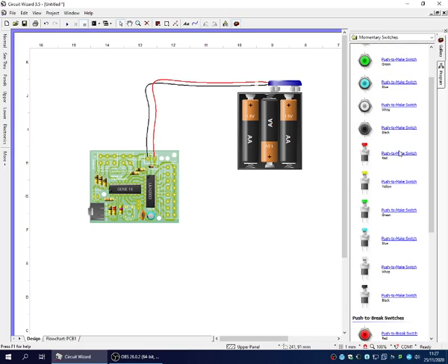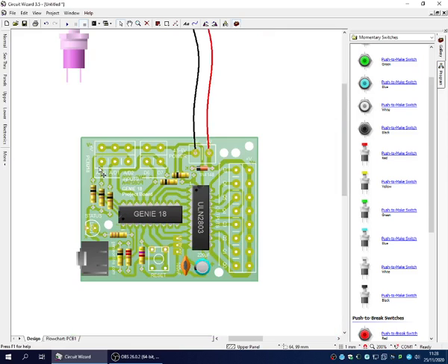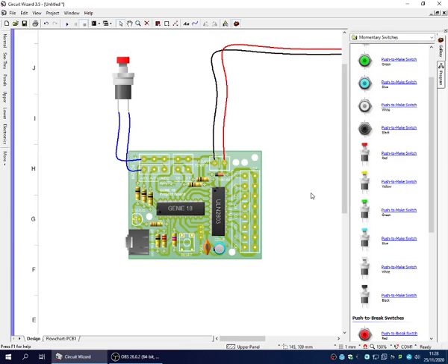Colours are relevant, obviously. So we're going to just plug this into our digital input. You notice here we've got A or D, analog or digital. So in this first exercise, we're just going to have a digital on-off. Now you could plug the colours, they're both blue. So one goes to plus volts and one goes to the digital input. So it means it's taking a 5 volt high, and when you make this circuit, it goes through a protection resistor into the input. Okay.